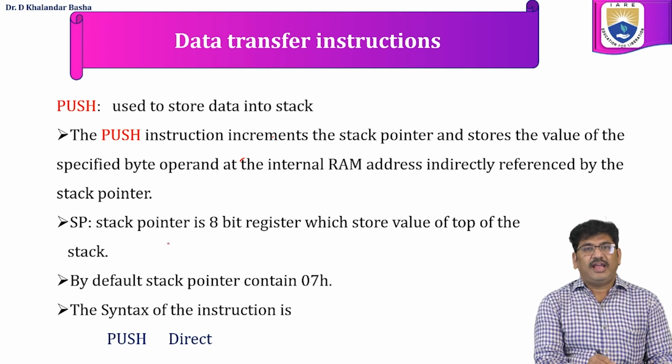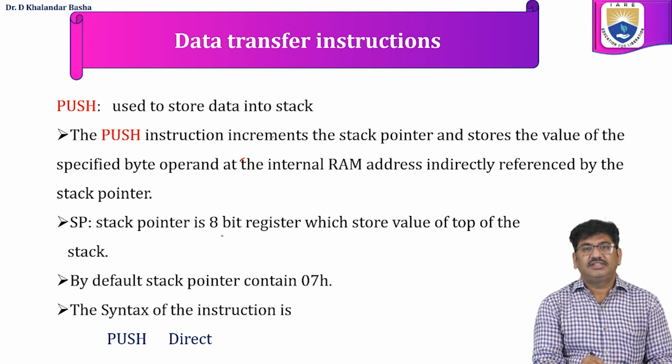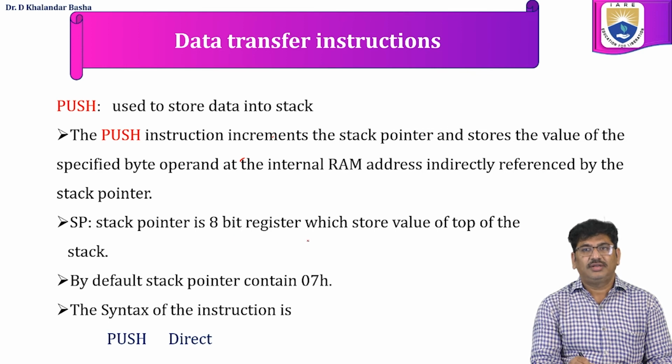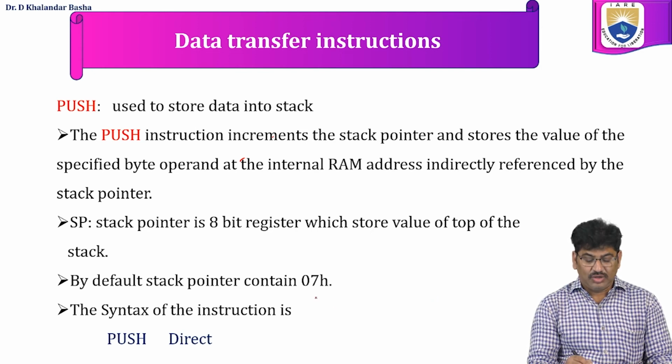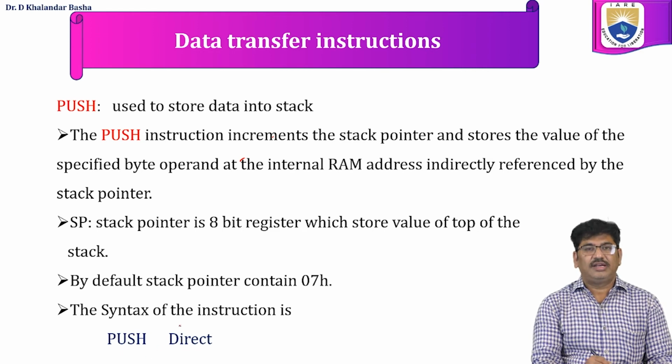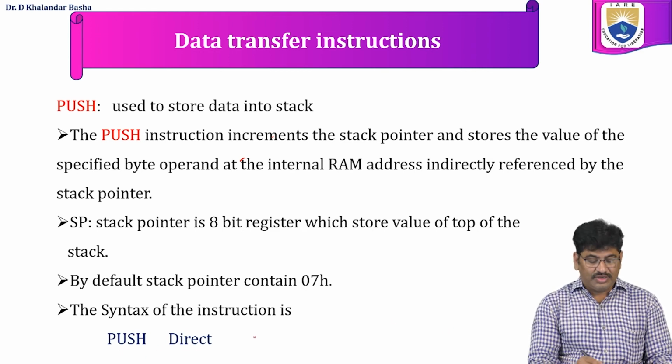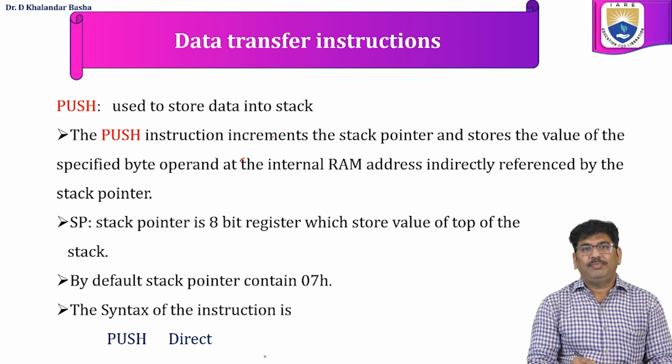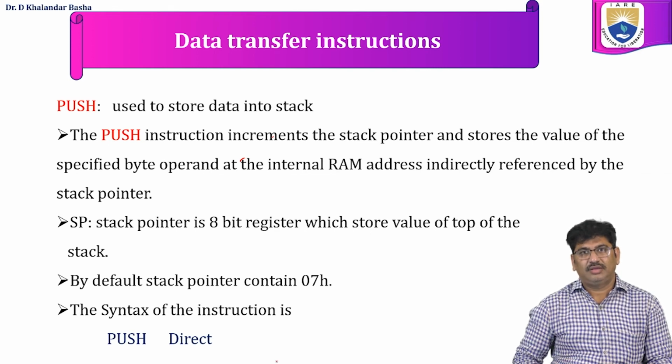SP stands for stack pointer, which is an 8-bit register that stores the address of the top of the stack. By default, the stack pointer is loaded with 07H. The syntax of this instruction is push direct. Whatever you have specified in the direct will be placed onto the top of the stack.